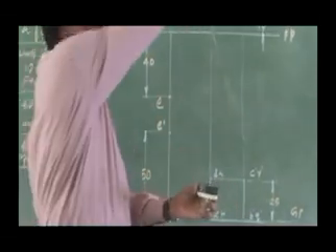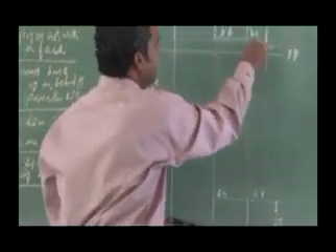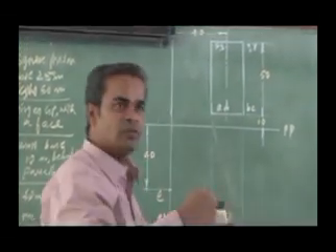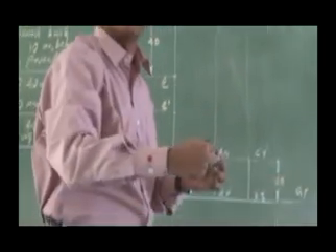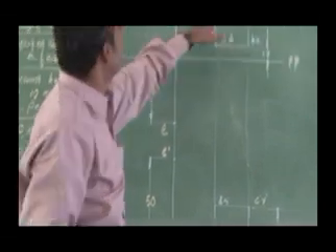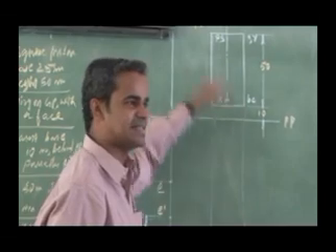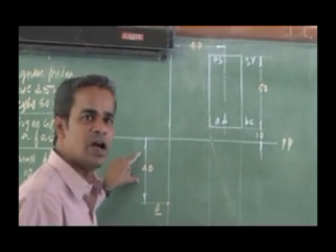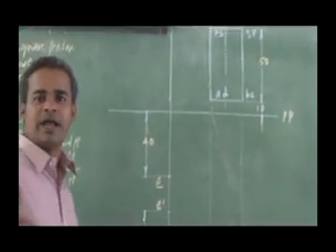So I have to draw the top view on the top. The top view will be a rectangle, and the base is 10 mm behind the picture plane. So what will be the front view? By projecting the top view, I will have the front view, which is nothing but my base. It is a square. I have drawn it. That is the difference. The remaining thing, the center plane, that is the station point, is 40 mm to the left from the axis of the solid, and the station point is 40 mm in front of the picture plane. At the same time, it is 50 mm above the ground plane.